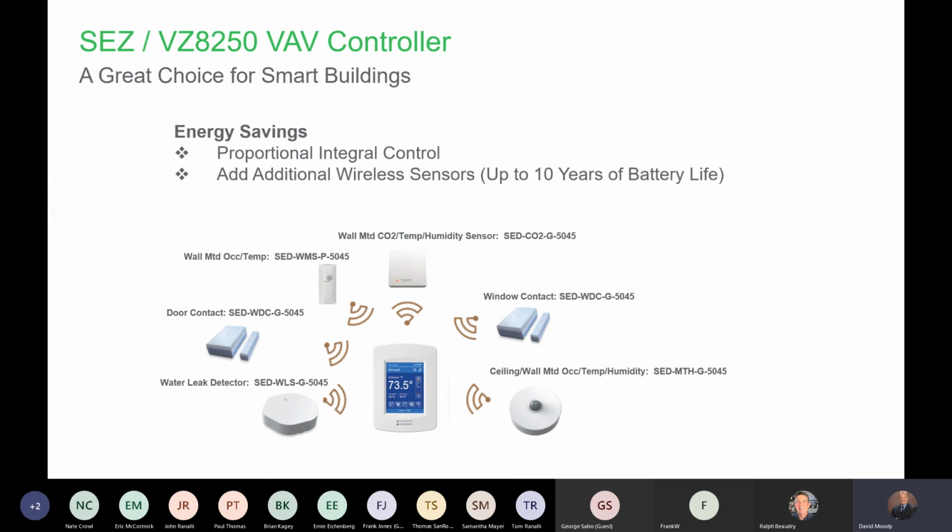I want to monitor the door and use that energy conservation measure that's built into the room controller, but I've got a Wi-Fi module installed in the slot. How do I make that work?" Well, you throw that room controller away and you buy a new one with the ZigBee radio on it. So it's just an option they provide folks.